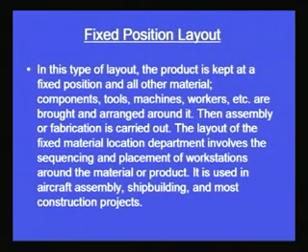So wherever a big building has to be created, fabricated, or developed, there we are not taking the building from one place to another. The building is being developed at a particular place and all the other equipment and machines go to that particular location. So that basically is the fixed position type of layout. Now we will see the salient advantages of this type of layout and the disadvantages or limitations of this layout.